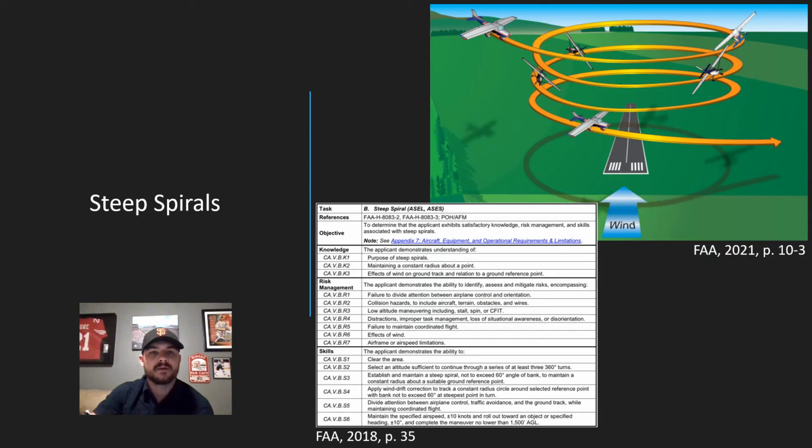Steep spirals are a gliding turn where the pilot maintains a constant radius from a ground reference point. It allows the pilot to rapidly lose altitude while staying over one spot and could be useful during emergency landings. While like an emergency descent, the reasons for using the maneuver differ and it is commonly done with a different airspeed and configuration. Operating at idle in a glide could result in excessive engine cooling, carburetor icing, and spark plug fouling. To prevent this, the throttle should be periodically advanced.